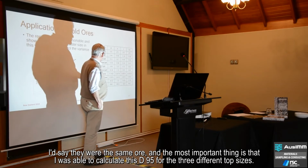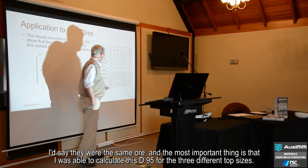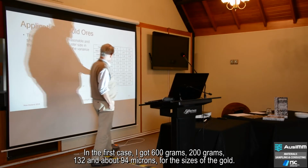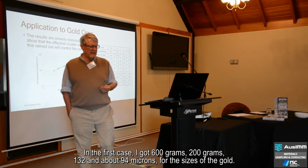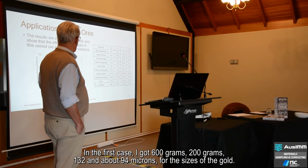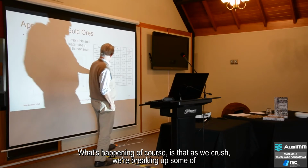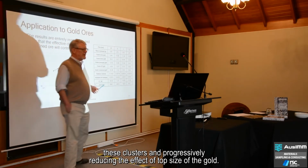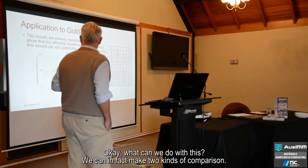And the most important thing is that I was able to calculate this d95 for the four different top sizes. In the first case, I got 600 microns, 200, 132, and about 94 microns for the sizes of the gold. And what's happening, of course, is that as we crush, we're breaking up some of these clusters and progressively reducing the effective top size of the gold. Okay, what can we do with this?